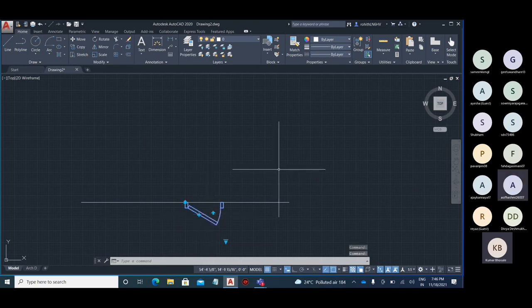There are two panels. So for both the panels to rotate at different angles, if we have to show both the panels opening at 30 degrees or 60 degrees, how many flip states do we have to create? You have to create only one flip state for the double door panels. Only one flip state.